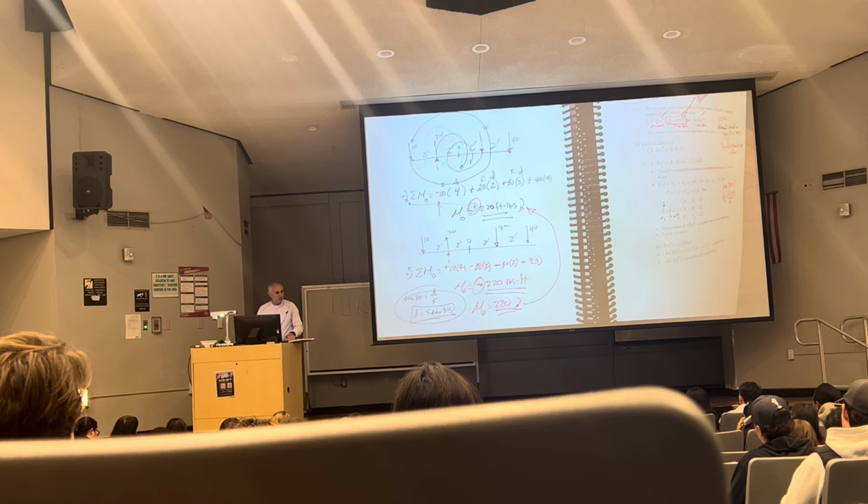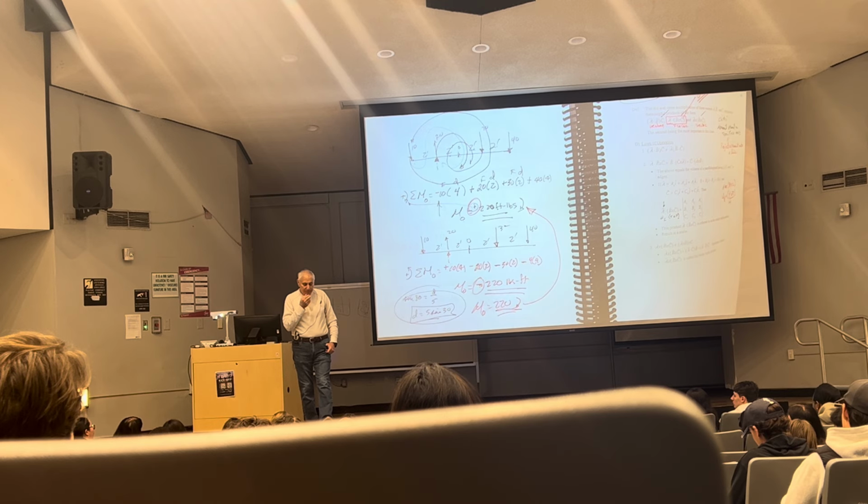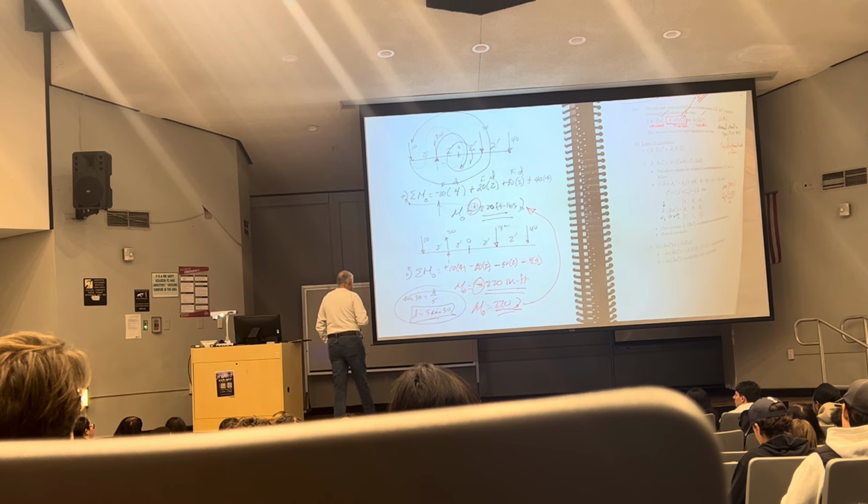Questions? Thoughts? Comments? Ideas? Anything bothering anybody? Yeah? So we use 5 times sine 30, that's 5 times 1 half. So then you multiply the 2.5 by 100, and then you get the 250 pounds. That's it. Easy.